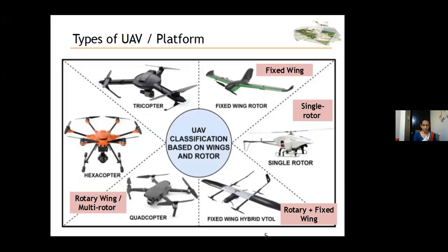The second one is the fixed wing drones, as opposed to rotary wing, that is actual helicopters. You can see one picture here. They use a wing like a normal aeroplane to provide the lift rather than vertical lift rotors. Because of this, they only need to use energy to move forward, not hold themselves up in the air. So these drones are much more energy efficient compared with the rotary wing drones.